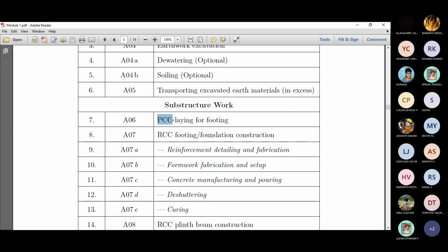The formwork is a temporary structure that gives the shape of the concrete, right? People call this shuttering also in colloquial terms, but formwork is the actual term. And other materials like accessories to formwork, generally the scaffolding and other elements, are called false work. So that's the difference that you should know. Probably you would have learned that in the construction materials and technology course, but I'll just repeat. Formwork is the temporary structure. It could be made of timber, steel, aluminum, and so on. Whereas false work or scaffolding, like hook block scaffolding, access scaffolding, is used for finishing works and something like that, right?